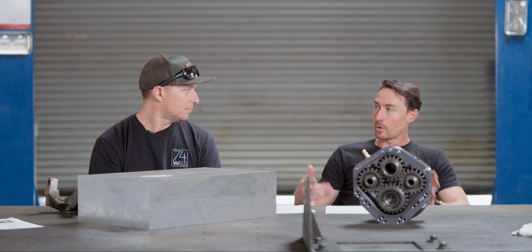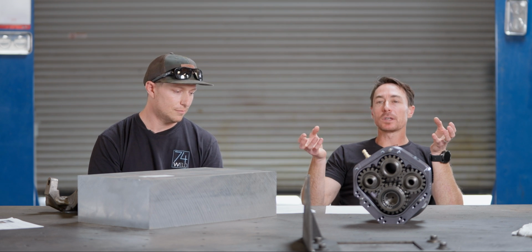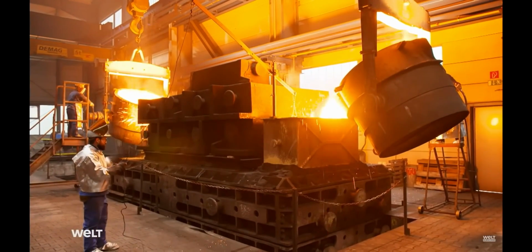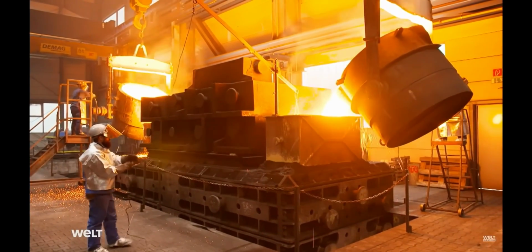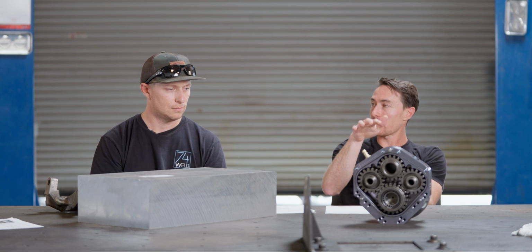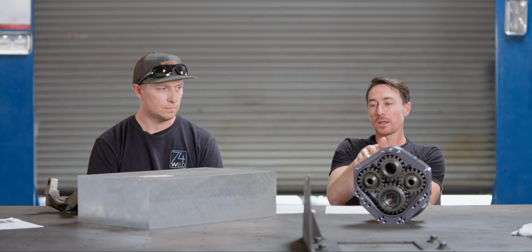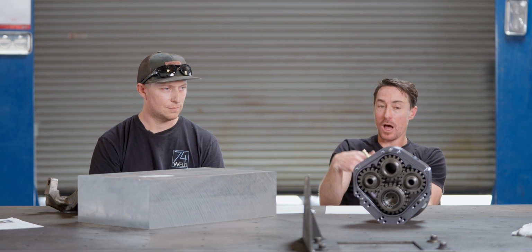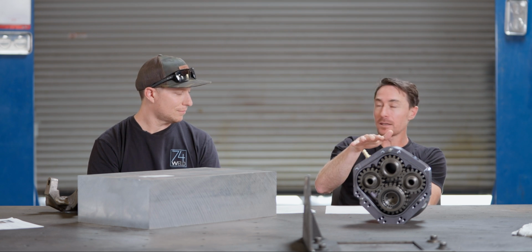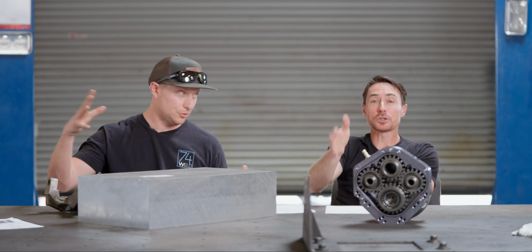You can also do a molten and then forged, but the easiest way to think of this is for casting, you're pouring a liquid in and it solidifies and now you have your part, okay? For forging, sometimes you're going to take a solid block and you basically are mashing the thing into the shape you want. Now you can also hot forge, where you have a heated block of aluminum or whatever material you want to forge. Yeah, it's super hot and you're squishing it all together.